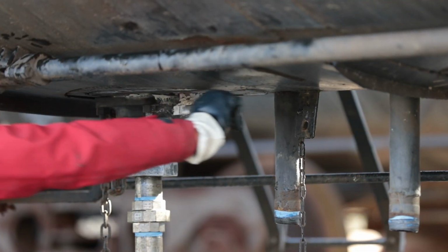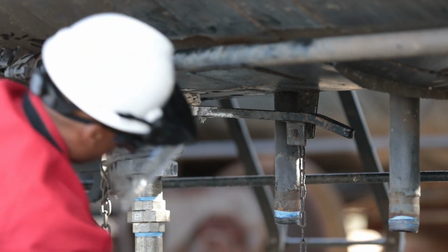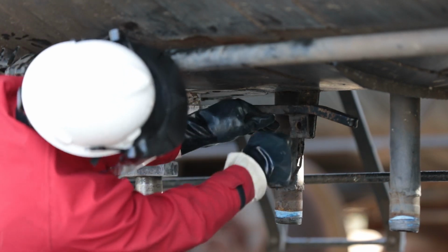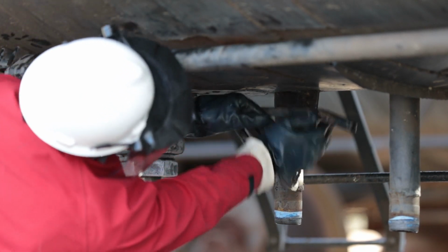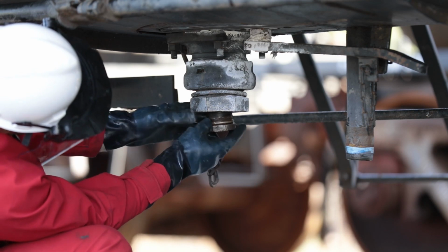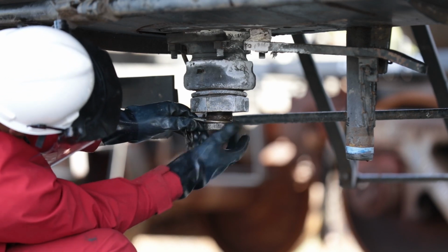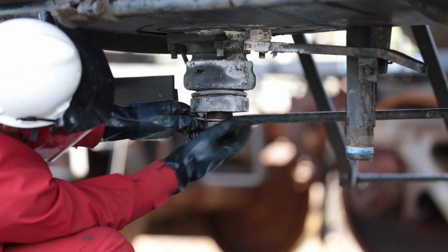If it is necessary to discontinue unloading a tank car for any reason, all valves should be tightly closed to stop the flow of caustic. Unloading connections should be disconnected, and plugs should be installed in the tank car valves.